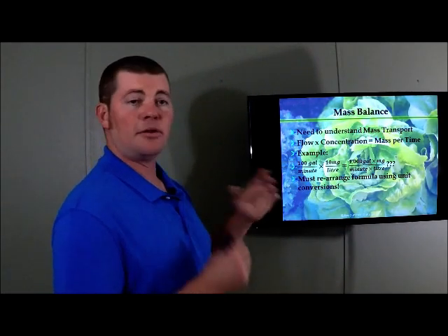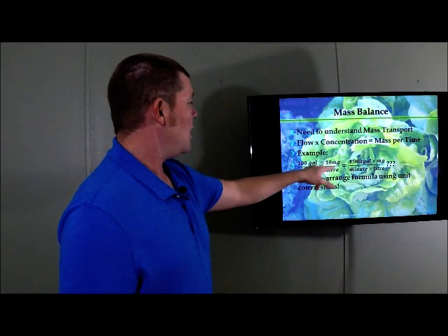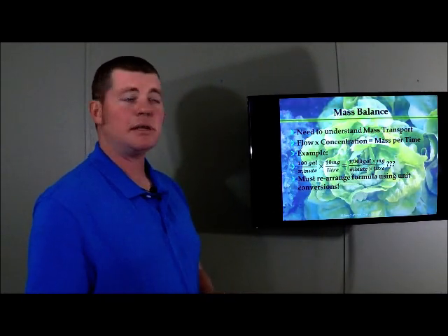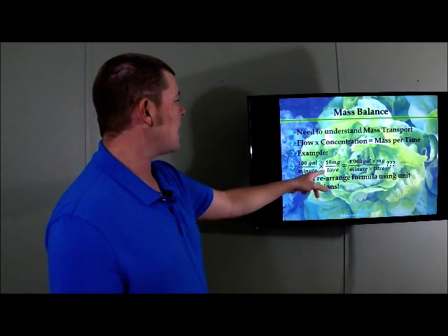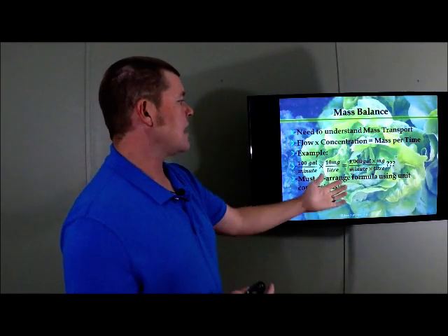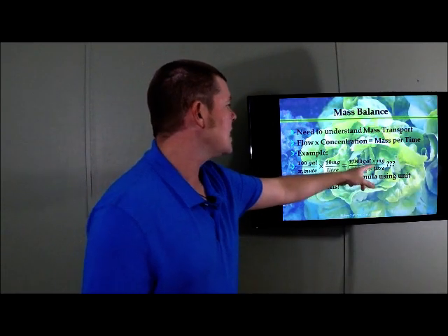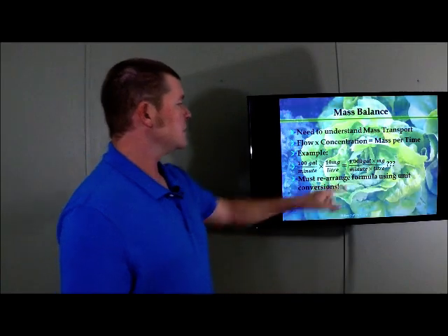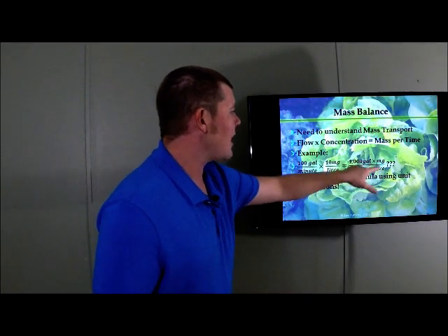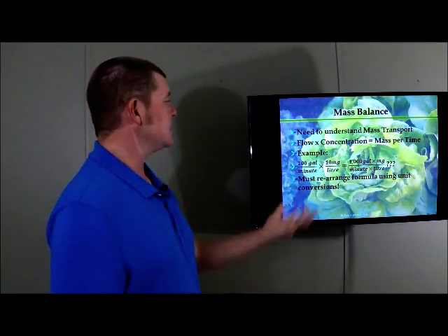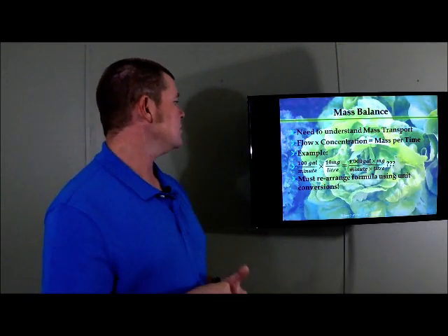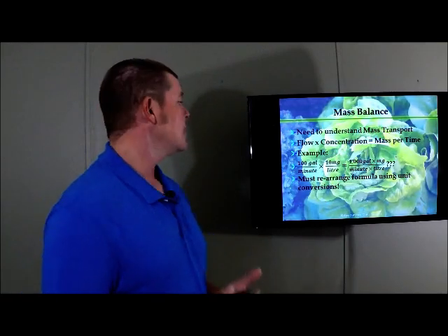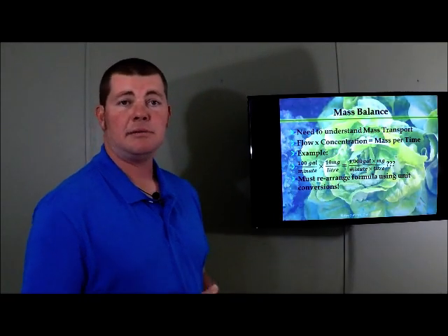100 gallons per minute, the flow. 10 milligrams per liter, how much oxygen is in that water, okay? That's pretty easy. Well, when we multiply these two together, we get something that does not compute. We get 1,000 gallons times milligram over minutes times liter. Now, there's nothing for these to actually cancel out, and that's not a true value. That doesn't tell us anything. So we need to rearrange these formulas and extrapolate this to give us the information that we need.